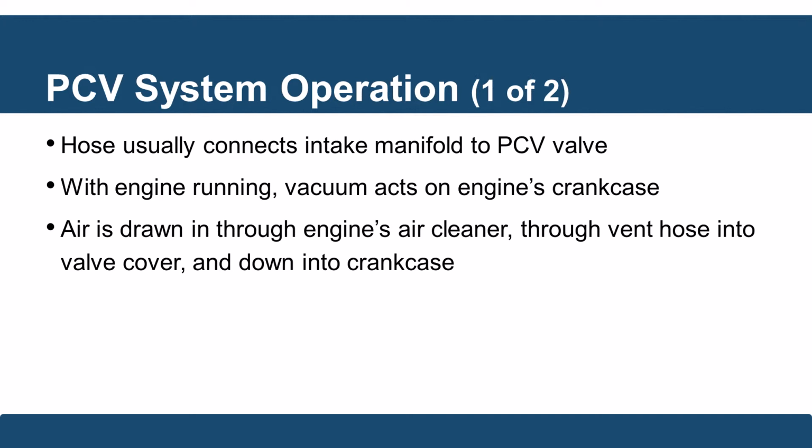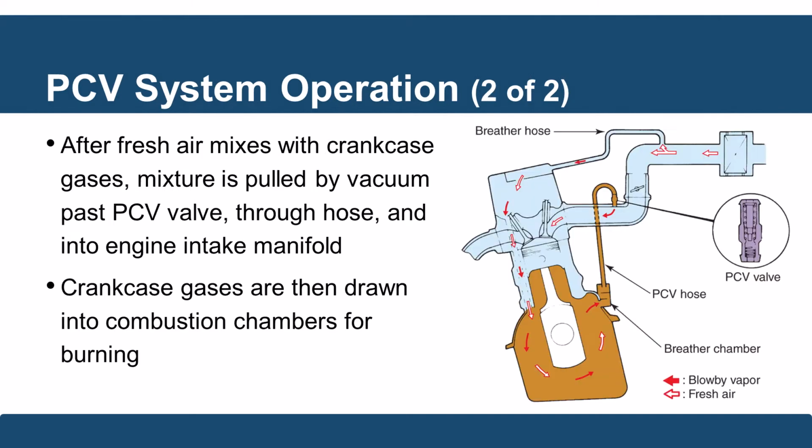With the engine running, the vacuum acts on the crankcase gases, and air is drawn in through the engine's air cleaner, through this vent hose, into the valve cover and down into the crankcase. We're going to pull those fumes in and burn those and actually use them as an energy source, which is a good thing. We're helping get them out of the crankcase.